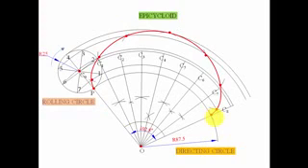Now guys, there was one more thing in this problem: we are supposed to put a tangent and normal at a certain point 125 mm from the center of the directing circle. So this over here is the directing circle, and this is its center, O. With O as center and a radius of 125 millimeters, we put an arc. This arc intersects the epicycloid over here, and hence this point is at a distance of 125 from O.